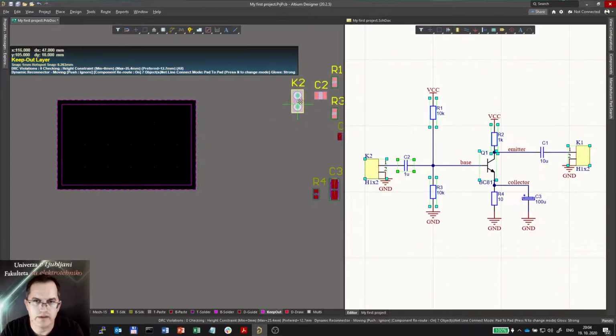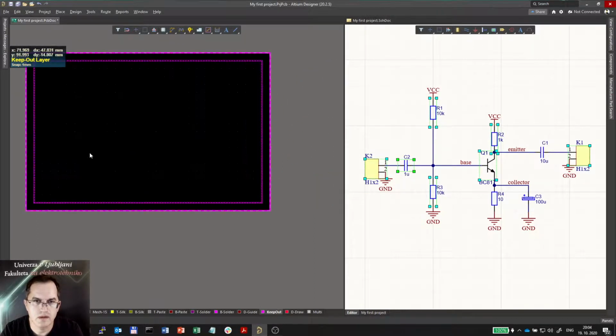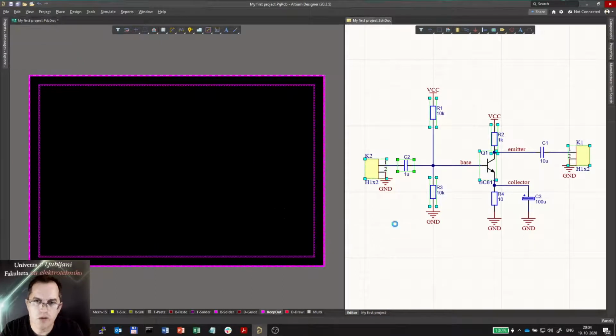I will go back there. And now I will select the components one after another in a certain order, starting here, pressing Shift, then that one, that one, that one, that one, that one, that one, and that one. Maybe here the transistor was not fully selected. I have to select it fully. So I'll start again. Pressing in the middle of the component is the right way. Otherwise, you can only select the pin.